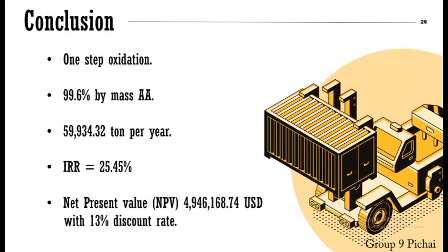On the other hand, the reaction in the Aspen Plus program is powered by using kinetic data of reactions, activation energy, and the K constant. The recommendation is that the data of the catalyst should be input to the Aspen Plus program for more accurate results. Therefore, the data of the catalyst of the one-step oxidation from propylene to acrylic acid should be researched and tested in the laboratory.